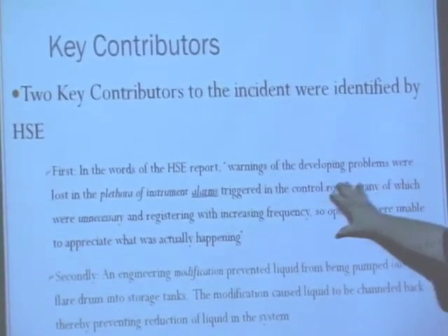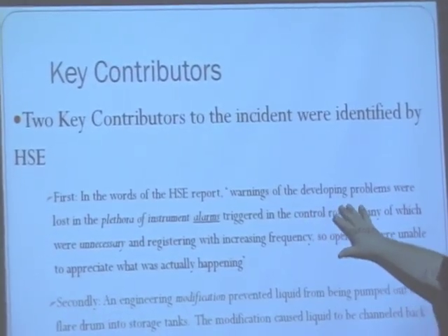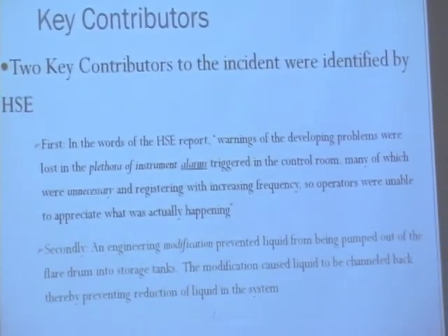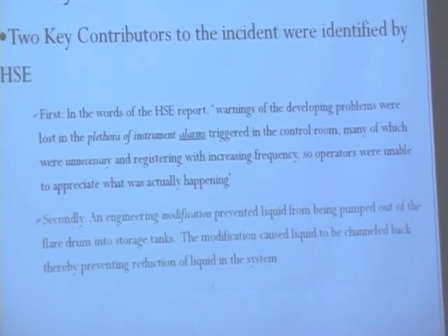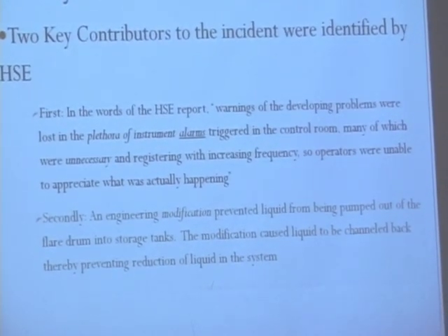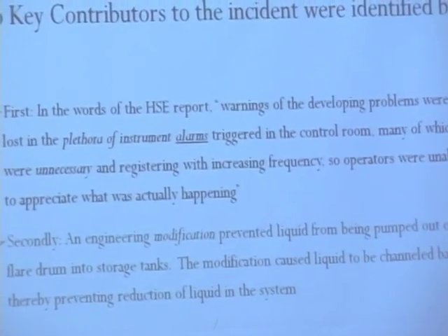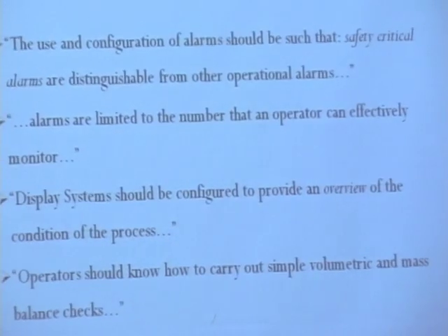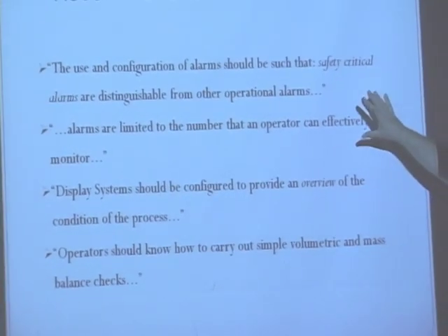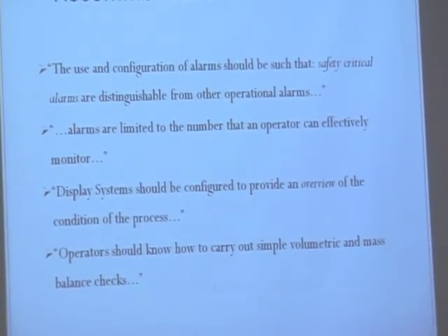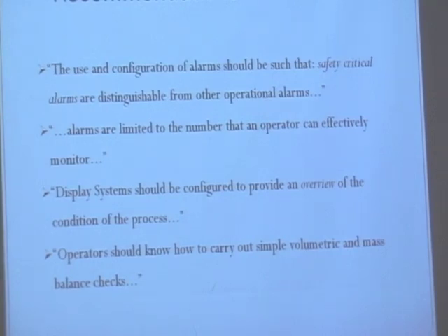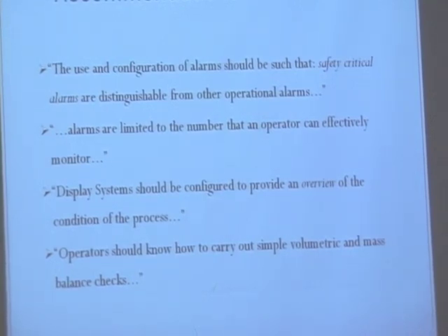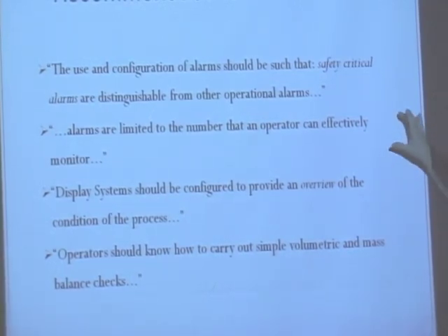Basically, this is one of the ones we want to focus on: the plethora of alarms triggered in the control room, many of which were unnecessary and registering with increasing frequency, so operators were unable to appreciate what was actually happening. And again, the use and configuration of alarms should be such that safety critical alarms are distinguishable from all other alarms. Alarms are limited to the number that an operator can effectively monitor.